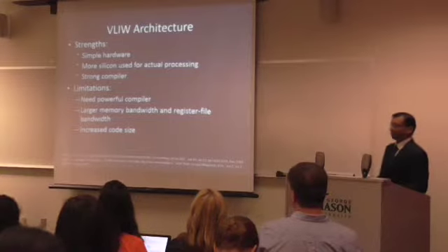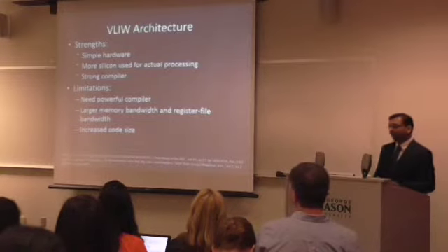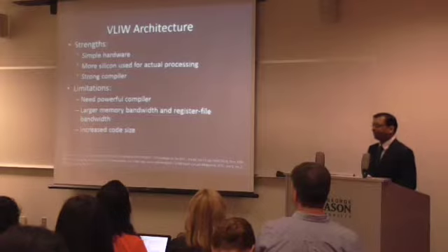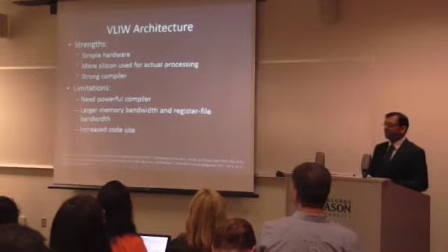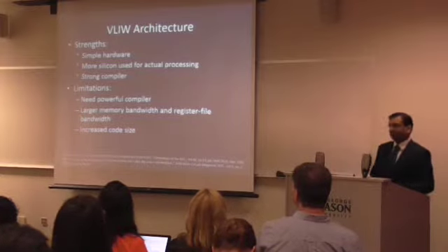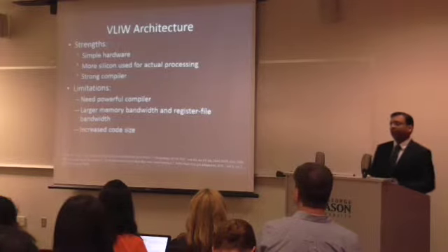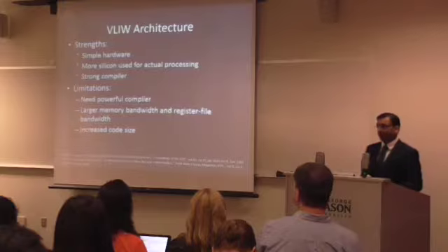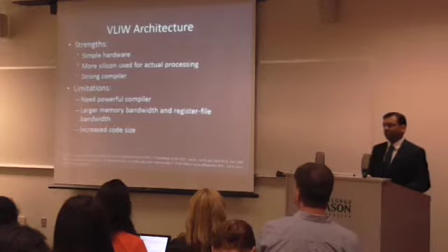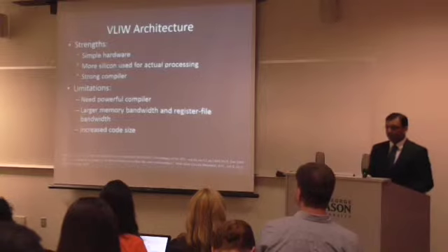So what is VLIW architecture? VLIW stands for Very Long Instruction Word. Basically, in this architecture, we design simpler hardware, but we design a strong compiler so that we can accommodate all instructions in a single long instruction and execute it on simple hardware.